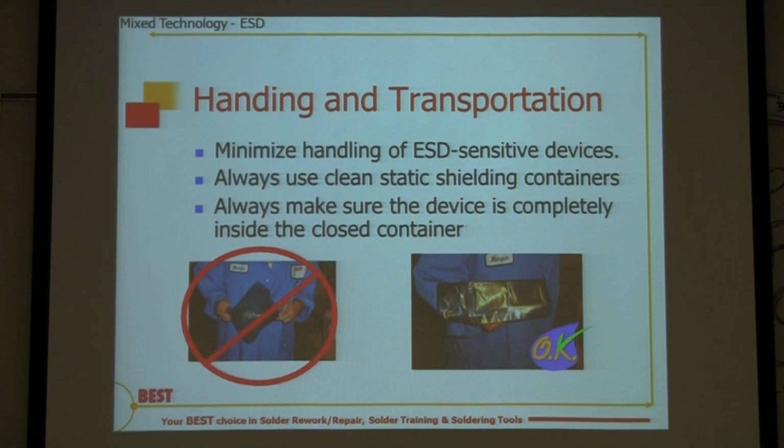Always use clean static dissipative containers. We explained to you earlier why. Always make sure the device is completely inside the closed container. Because if it's not, it's not protecting anything whatsoever. Come on, think about this.